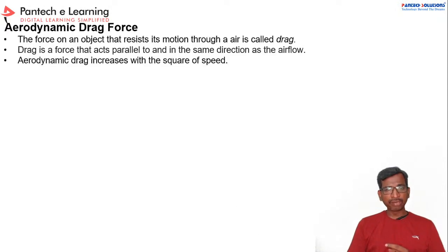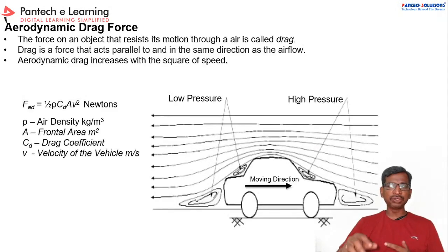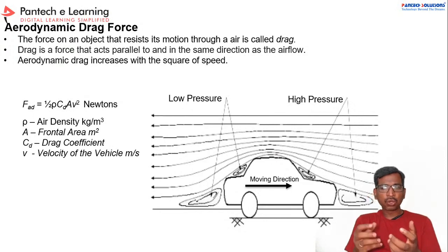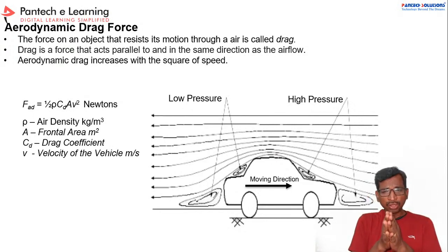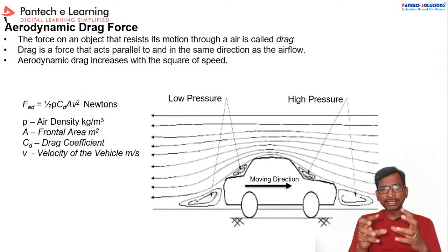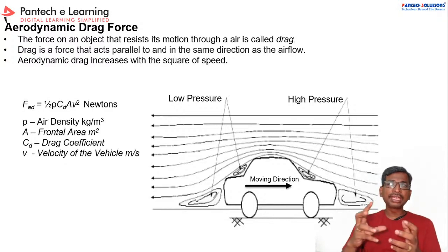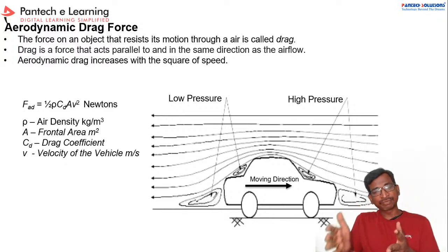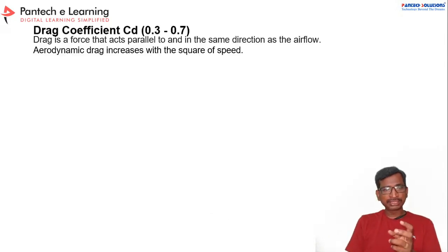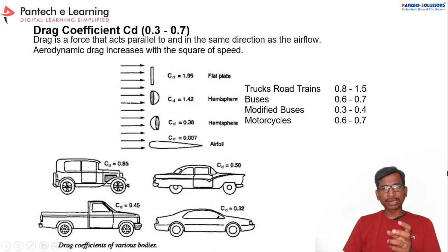Similarly, the aerodynamic drag force. This force generally acts due to the wind velocity. Again, this depends on your vehicle design. If you allow your vehicle to pass through the air, your design should not create a huge pressure on the front side of the vehicle. So in that case also you have to choose the proper design and the proper coefficients. Generally, for different types of designs you have to choose different values.